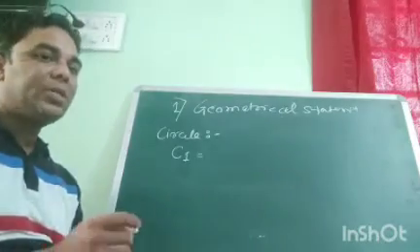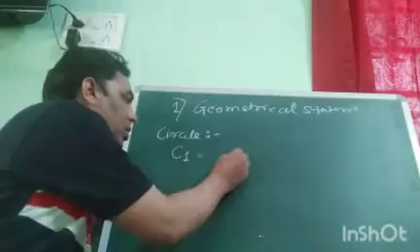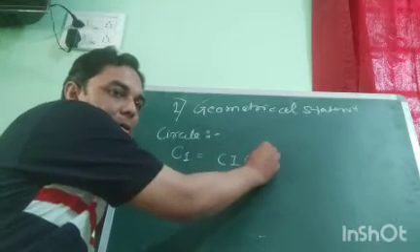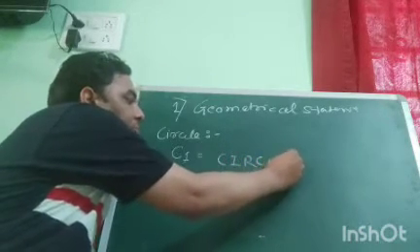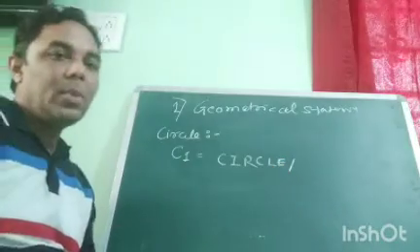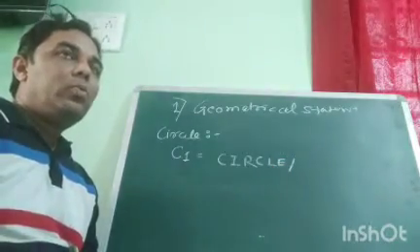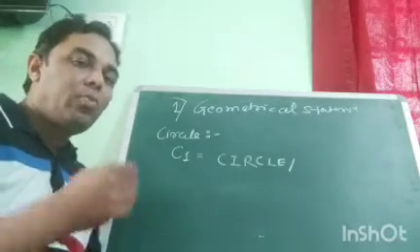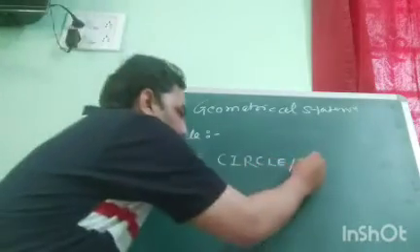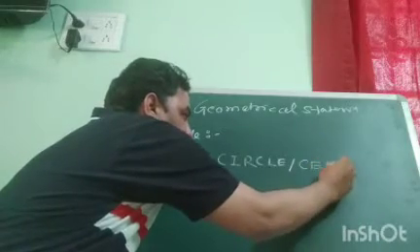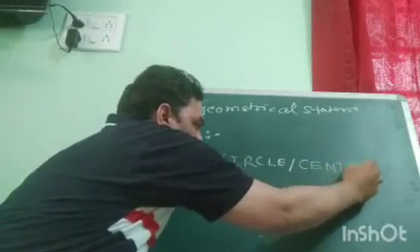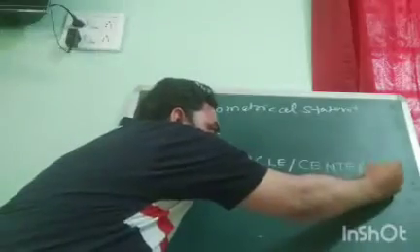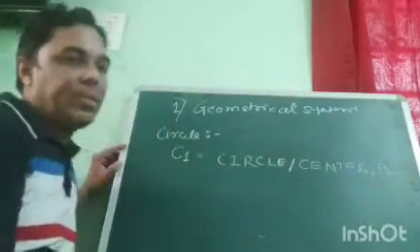In APT part program, we need to take the two essential entities, the point and the radius. So we just write CIRCLE. Then what is the center point of that circle? We should mention the center first. For example, the P1 point is the center of it.